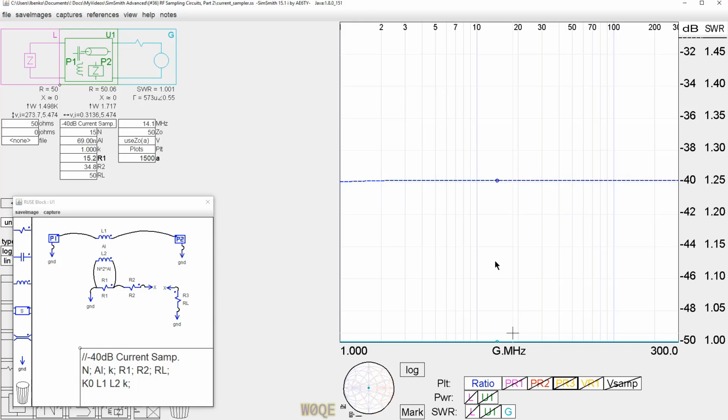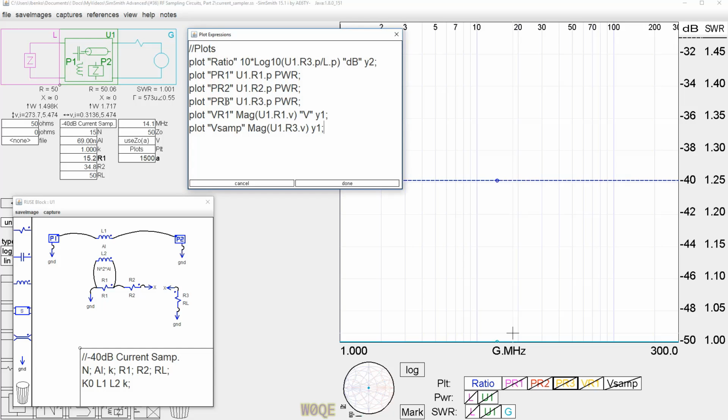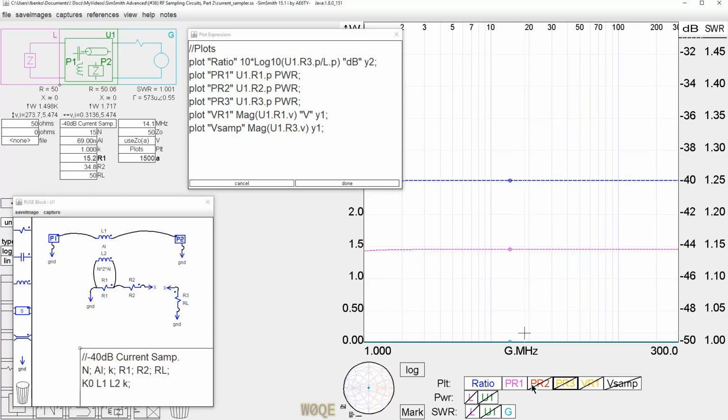We discarded those circuits early because they had faults. So far, this circuit looks to be pretty good. The next thing we want to do with the circuit, though, is look at the power in the circuit. The resistive circuit that was a voltage monitor looked pretty good, too, until we looked at the resistors and saw that we had 20, 28, or 29 watts with a 1500 watt source. So, again, I plotted all those powers here. Let's look at them.